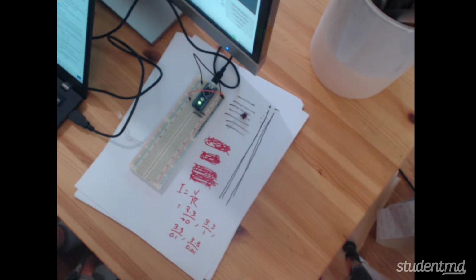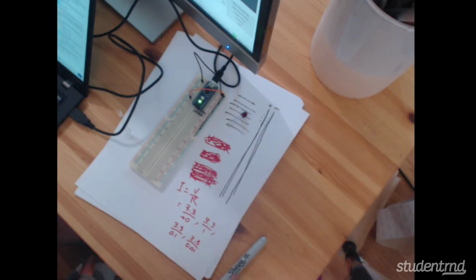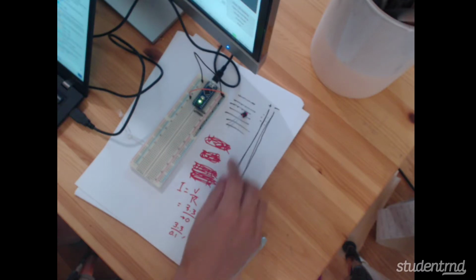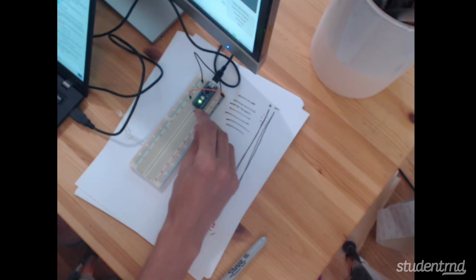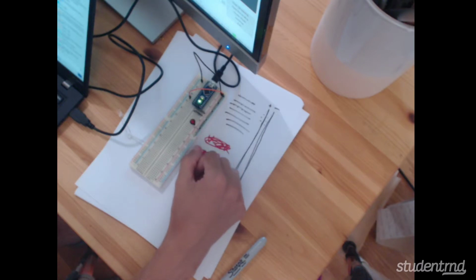current. For context, current is the thing that will really produce heat in addition to light. And even in wires, the resistance of wires will start to heat up once you're drawing a certain amount of current. So you can't have this much current going through an LED. It's just going to burn out. It's just too much. And so because LEDs generally do not have a very high resistance at all, we need to use a resistor to increase the resistance.